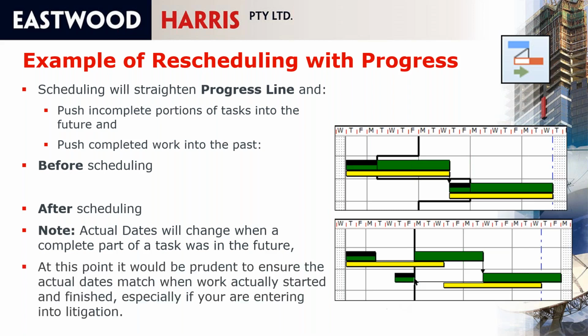At that point in time, I think it would be prudent to adjust the actual start of this bit of activity here to make sure it starts when it actually did start. But P6 would not move this complete work into the past.